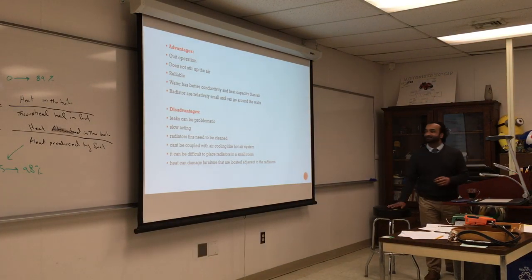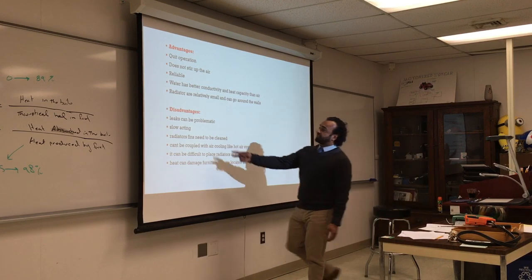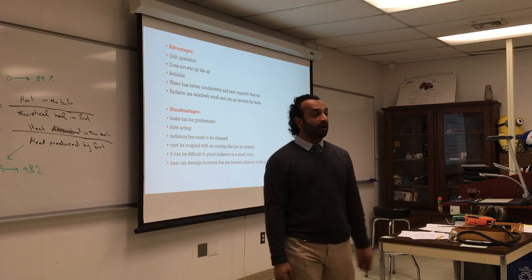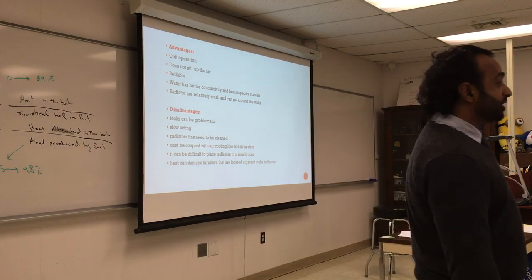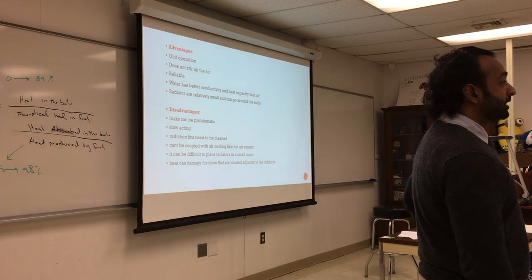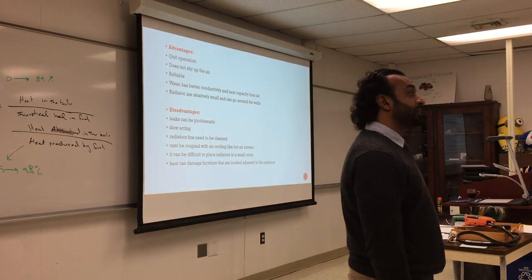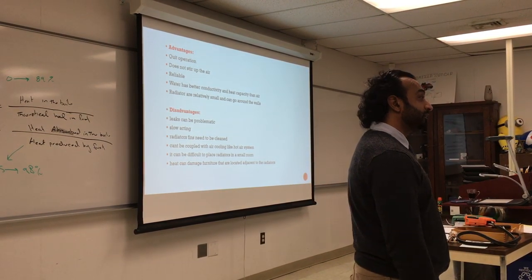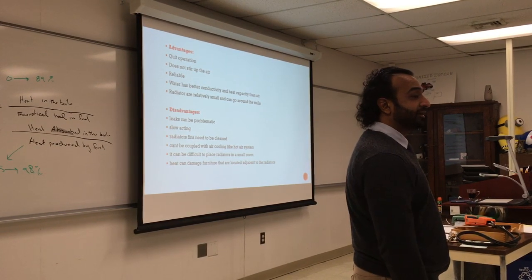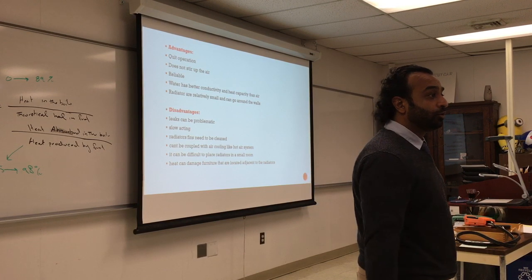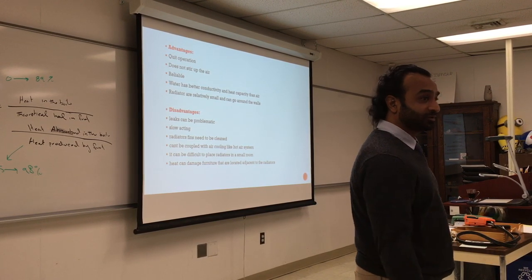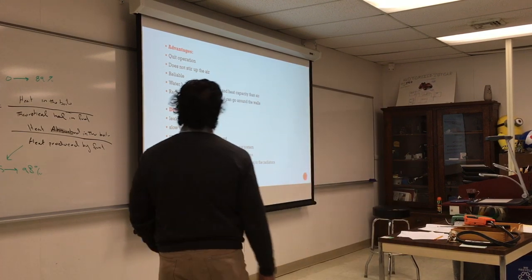There you go. So, disadvantages: leaks can be problematic. That's why you want to make sure that you have good soldering and you test the system before you put water in it. And also, when you change a component, make sure you test the system before you put water in it. And leaks, even though they could be very small, could be very damaging because it's going to go through your ceiling. Even if it drips one drop a minute, that over time could be an issue.